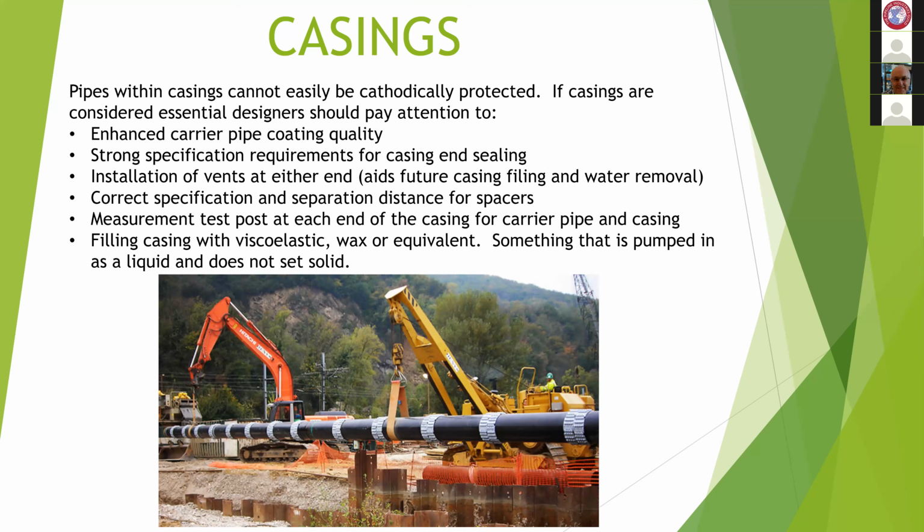If you're connected to the carrier pipe and to the casing, we can take various measurements and assure you that there's still no contact. And increasingly now, people are filling the casings with viscoelastic materials or wax-derived materials or equivalent, but it should be something that's pumped in as a liquid and does not set as a solid, which is the beauty of the waxes and the viscoelastics. They can easily be removed.